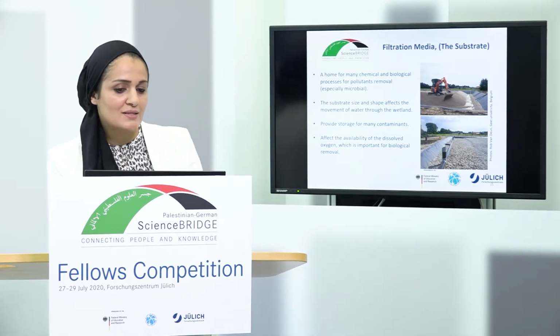The substrate size and shape also affect the movement of the water through the wetland. It provides storage for many contaminants, and it affects the availability of dissolved oxygen that is critical for the microorganisms to do their jobs by degrading the organic matter.